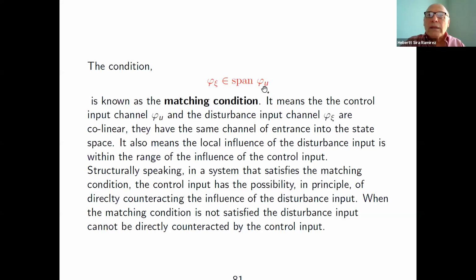And one way to attenuate them is to relegate them to the same channel, even though that means more complicated disturbances, and estimate them. The estimation is going to be approximate. It's never going to be a precise, exact estimation of the disturbance because you don't know the model of the disturbance. You cannot have a perfect estimation of the disturbance.